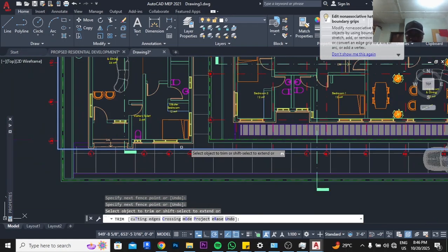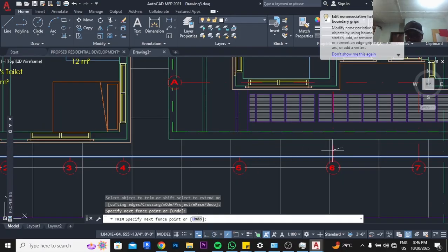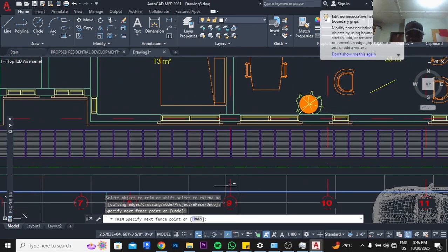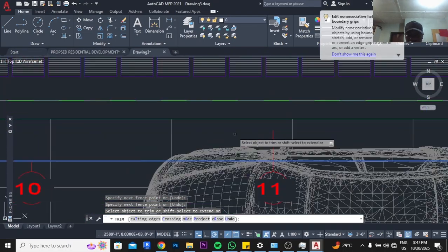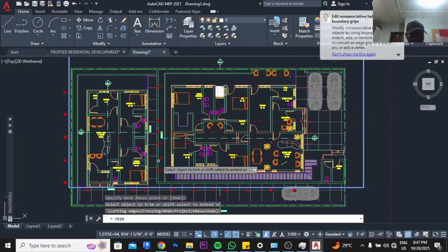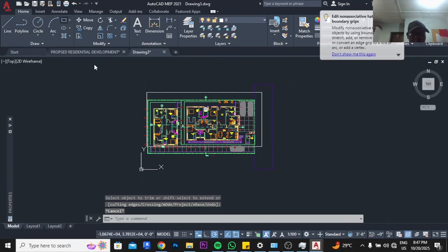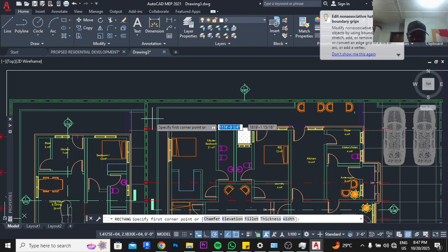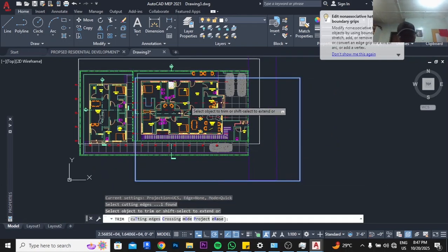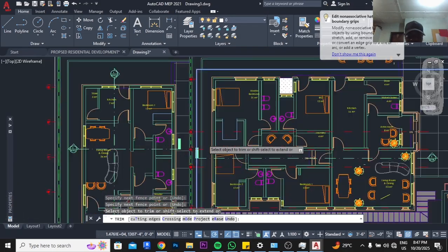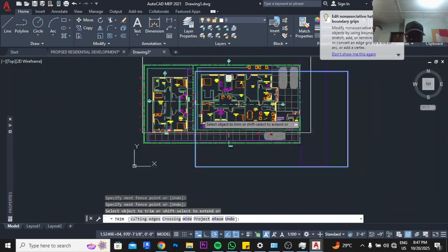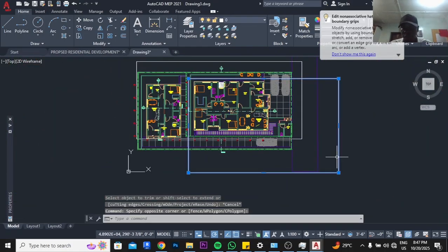So done deal. It's remaining this other guy. So I can as well draw a rectangle just to trim those guys out. Select the rectangle and click on trim. With that, it's very easy for me. So the work of this rectangle, they are done.